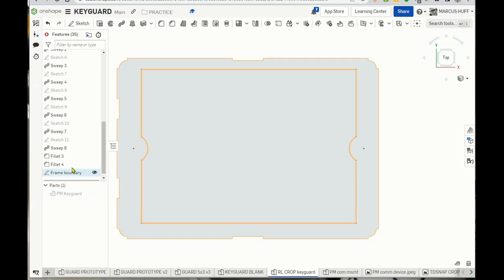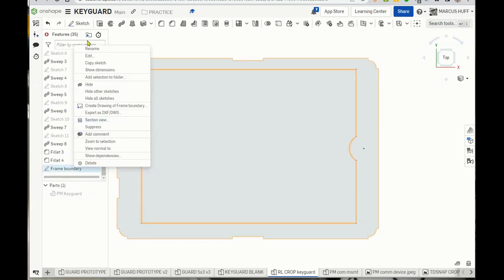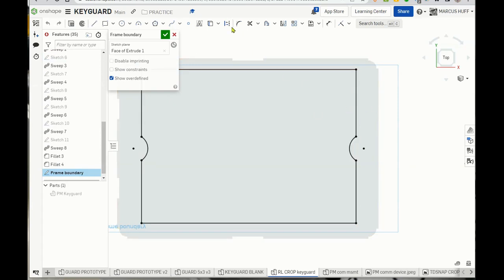I'm going to keep editing this sketch, and since we've got it in place and we've got everything else hidden, I'm going to use a construction line, and just draw a line. So we're drawing construction lines, and I'm just going to randomly run some across from one side to the other. So we have one, L for line, we'll do another one, and we have to have 5 lines. We also need that to be a construction line. What changes this to a construction line? Q. So we're going to use the commands L and Q.